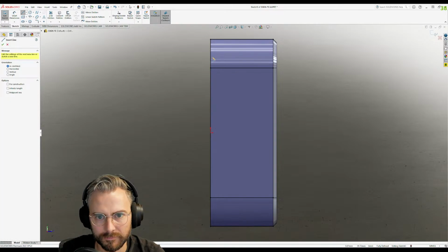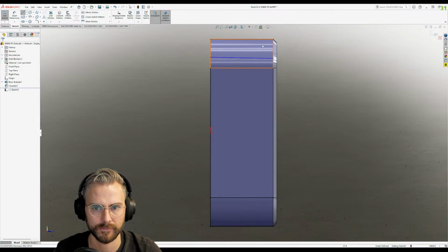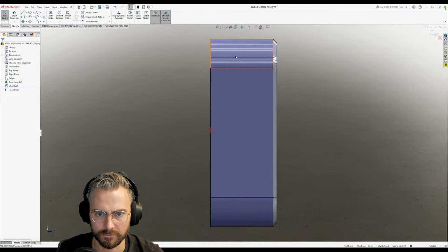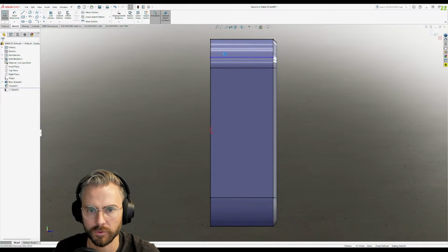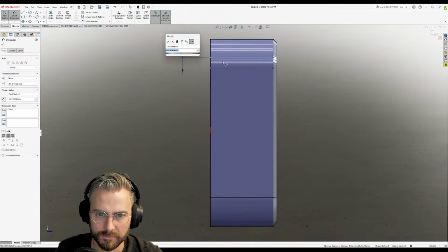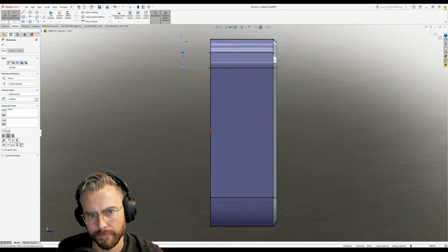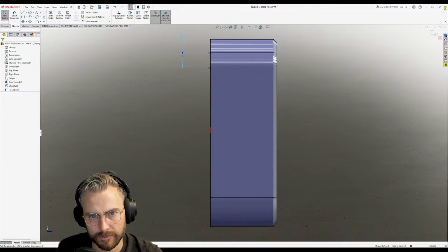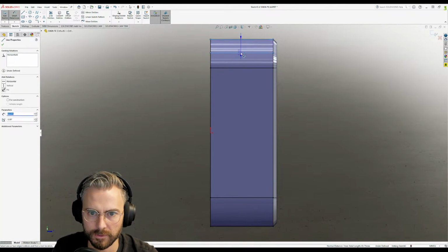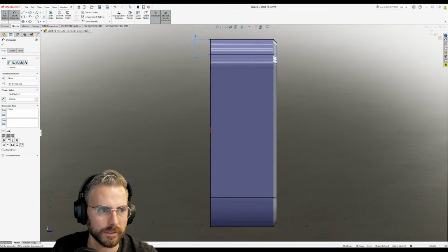So basically we're going to go here to here. That's not straight. So we are going to make that horizontal. Now it's straight. Oh, where are you on that point? I don't want you on that point. I want to dimension you to define you. So sometimes it'll snap to a point and it'll define something for you. But yeah. Oh no, it's not 8 there. It is actually 8 from the top of the radius. So we're going to go 8 here. 8 mil, boop.